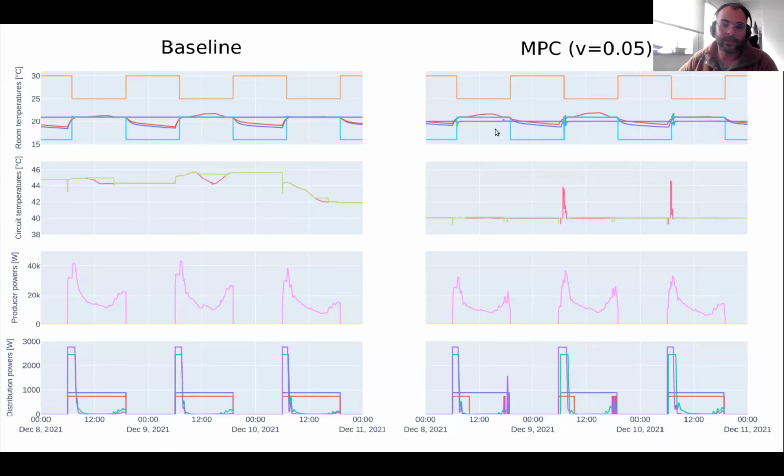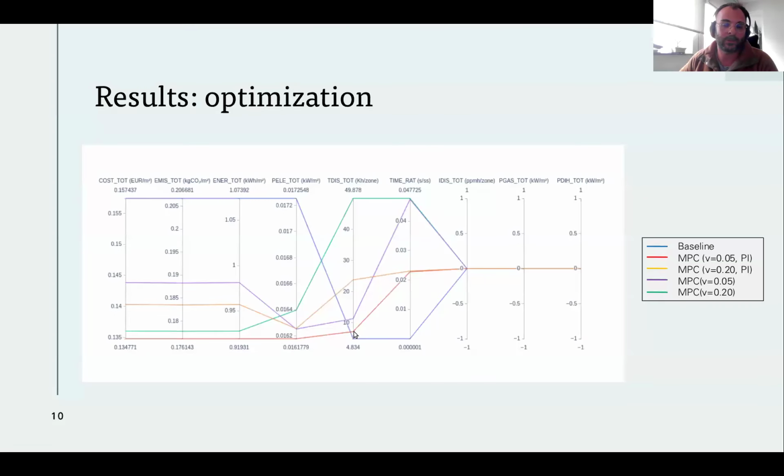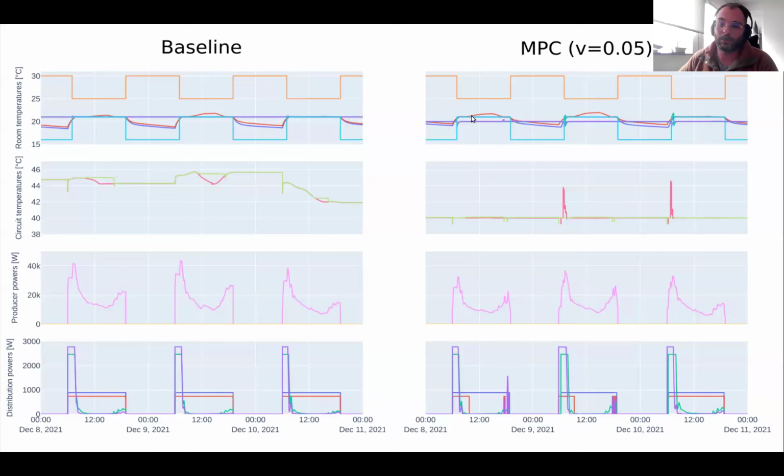And here the comfort changed from 4.8 to about, I think, if I remember correctly, 7. But if I see this solution in real industry, for me, this is a perfectly valid solution. Even if you get a bit of discomfort in the morning, normally at 7 a.m. the building is not that much occupied, and people normally walk into the office and their metabolism increases. We normally never get a comfort complaint because of this. If I get this result, for me, it will be totally valid for the industry.